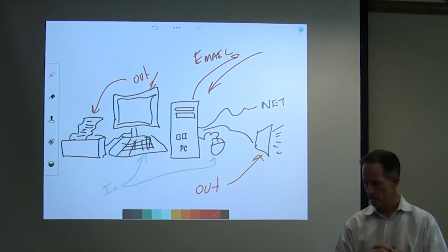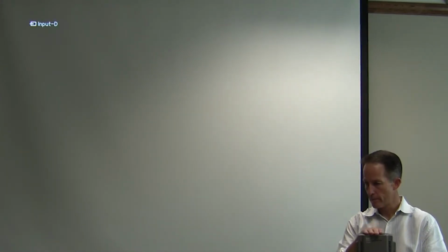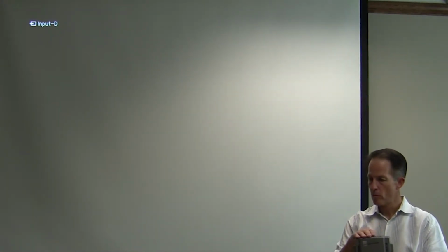Okay, well, you've got to see it from the JACE's perspective. So here's my controller. We're going to bring it in as an input. You'd add an input from the controller, wire a sensor into the device through a 10-volt input, and then configure the base and the gain so that you see the right value. So there's some configuration we do in this controller. We'll come back to the types of controllers in just a minute. We configure that input, and then you add an input in the JACE for that card.